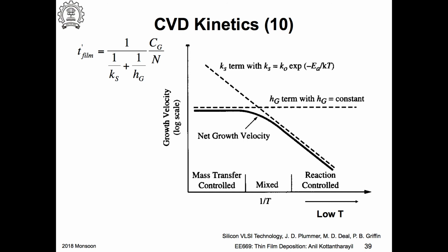That is why I want a slanted surface on which I place my wafer. The boundary layer thickness is constant throughout, so I would get wafer to wafer repeatability in the process. This is something we have already discussed. The thicker the boundary layer, the more time it takes for the reactants to diffuse through it.